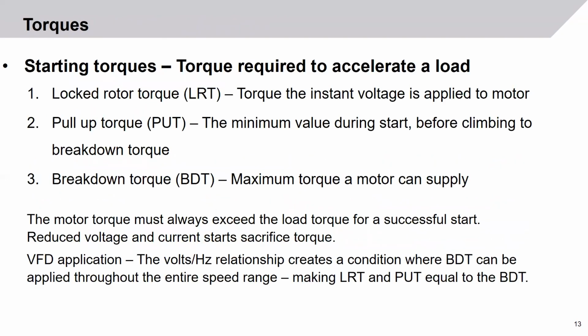Torques. Now there's also starting torque, which is the torque that is required to accelerate the load. The two specifically that we need to be concerned with are locked rotor torque, which is the torque the instant voltage is applied to a motor, and then there's pull-up torque, the minimum value during the start of the motor before it climbs up to breakdown torque. Breakdown torque is the maximum torque a motor can supply running close to its rated speed. The motor torque must always exceed the load torque for a successful start.